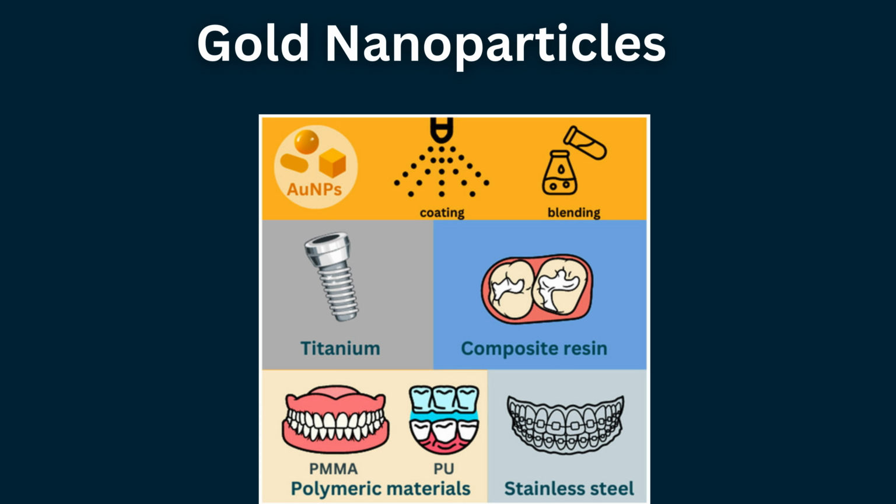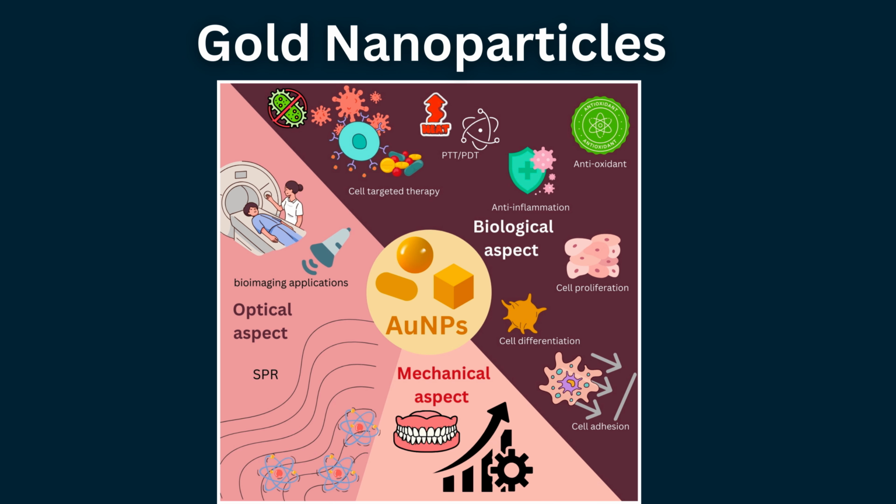Gold nanoparticles. Gold nanoparticles possess excellent chemical stability, biocompatibility, and antimicrobial properties. They can be incorporated into dental adhesives as colloidal dispersions. Increasing nanoparticle concentration improves flexural strength and diametral tensile strength by inhibiting crack propagation. However, excessive loading may cause particle aggregation, creating stress concentration sites that initiate cracks. Gold nanoparticles also demonstrate potential for bone regeneration, which may contribute to tissue healing around restorations.